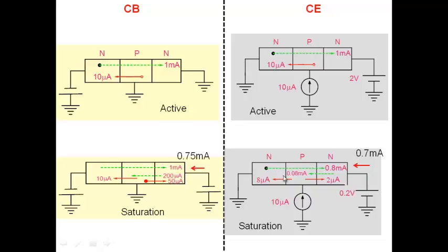The base emitter junction, this is where an issue comes in. Issue in the sense that, we keep on saying when the diode is forward biased, the voltage across is 0.7. Right? You've all seen now, 0.7 is an approximation. And we keep on thinking that it is 0.7, and therefore once it is forward biased, it remains so. But what is happening is, even though let's say this voltage was 0.7, the voltage slightly decreases here across the base emitter junction. Why? Because there's less current available here. Less current means less voltage here.